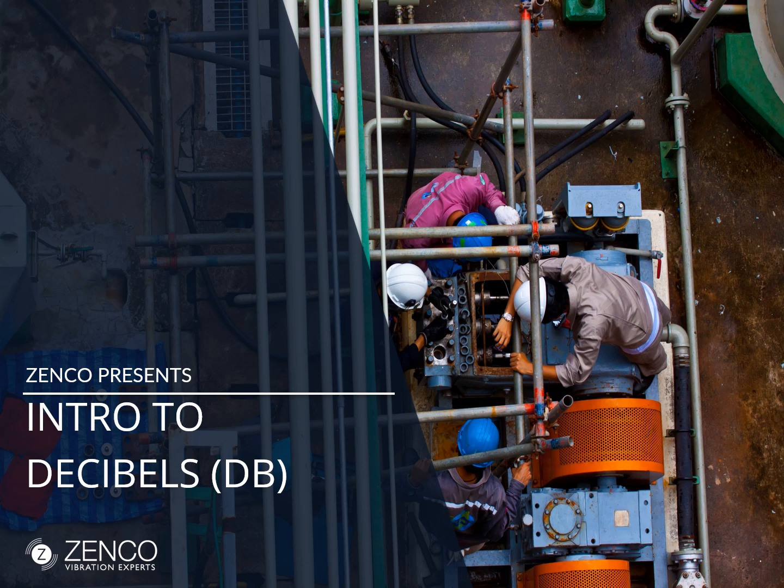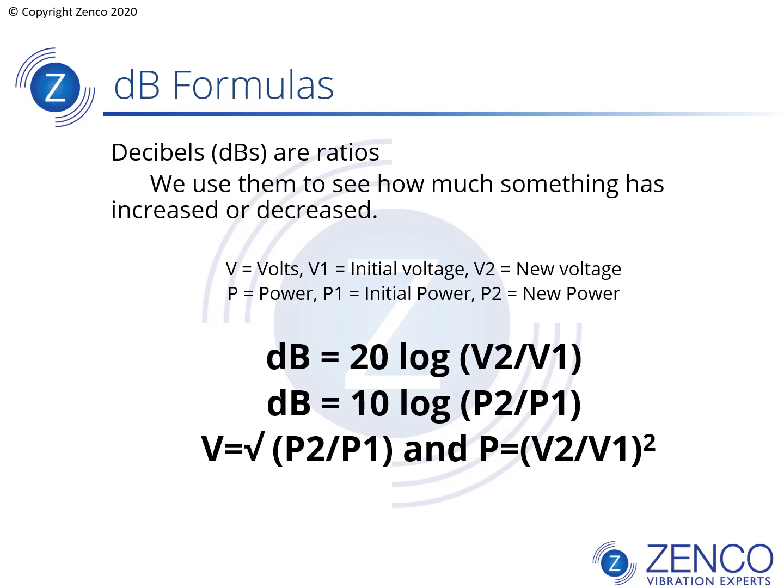Hey there, this is going to be a quick introduction to decibels, or dBs, and where you see them in vibration analysis. Decibels are ratios. We use them to see how much something has increased or decreased. Sometimes we talk about the voltage, for example, the voltage coming out of a sensor, and other times we talk about power. These are the formulas that we're going to use to understand decibels.